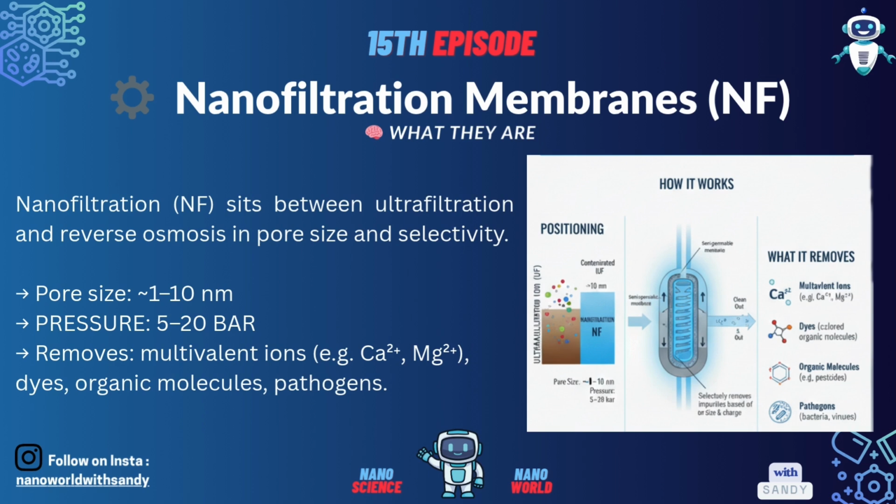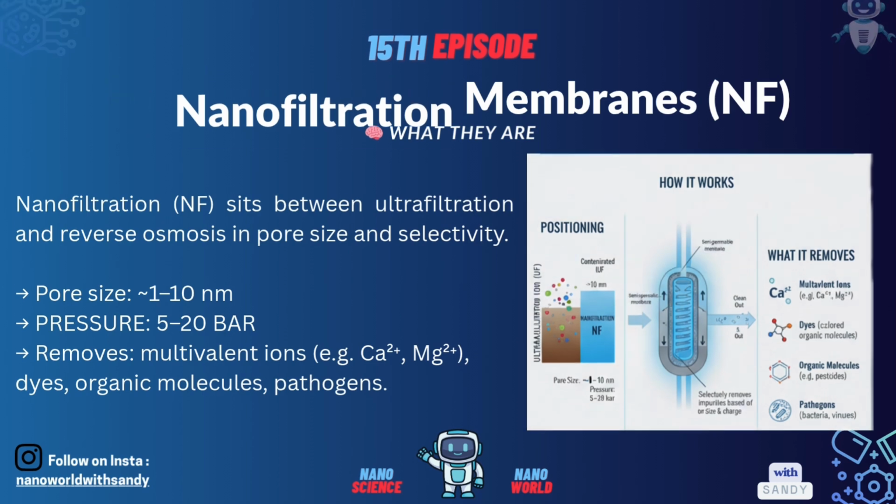Nanofiltration is the Goldilocks of membrane technology. With a pore size of about 1 to 10 nanometers, it operates at moderate pressure, about 5 to 20 bar, making it far more energy efficient than reverse osmosis.